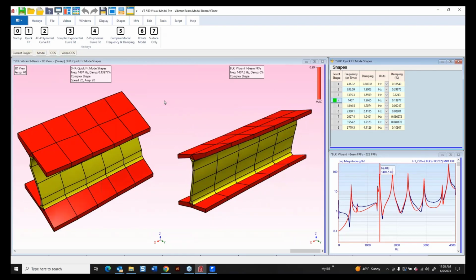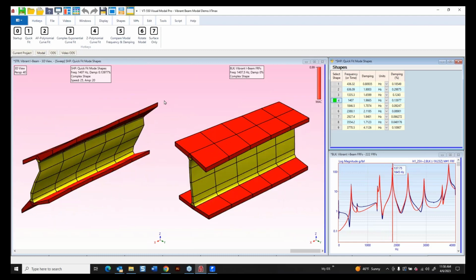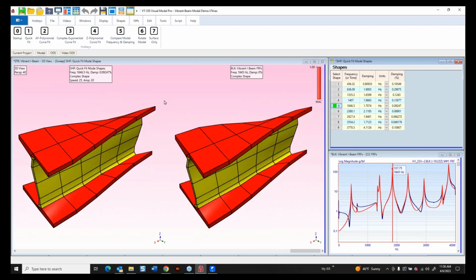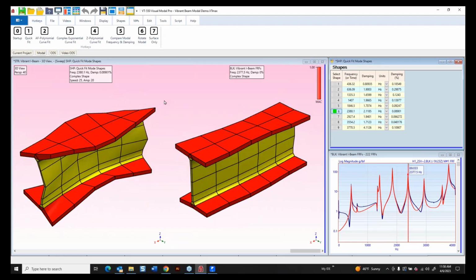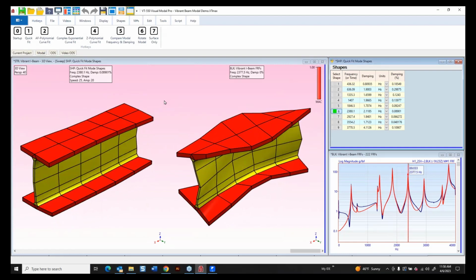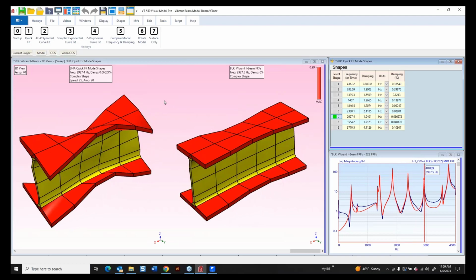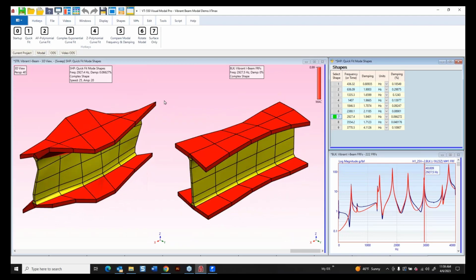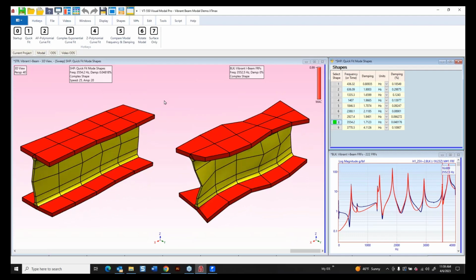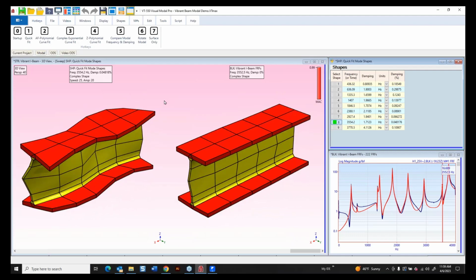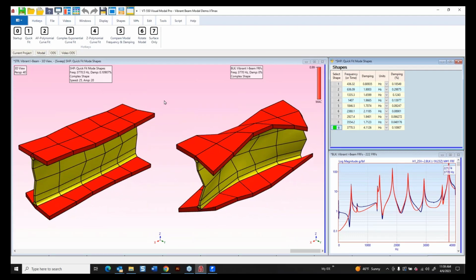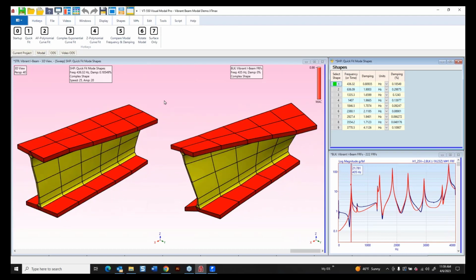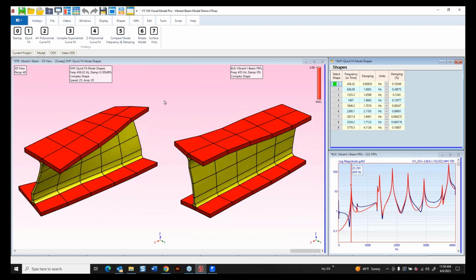Now the advanced curve fitters, I think, will not allow negative damping, and we'll look at that next time because we use a stability diagram, and the damping values all have to be within certain tolerances, and I think they also have to be positive damping. So in the real world, any damping that a mode would have associated with it should be positive damping.